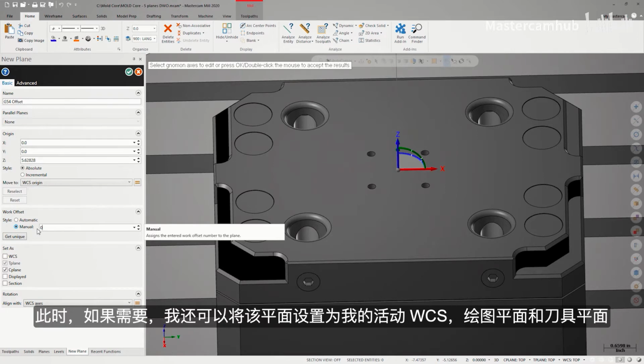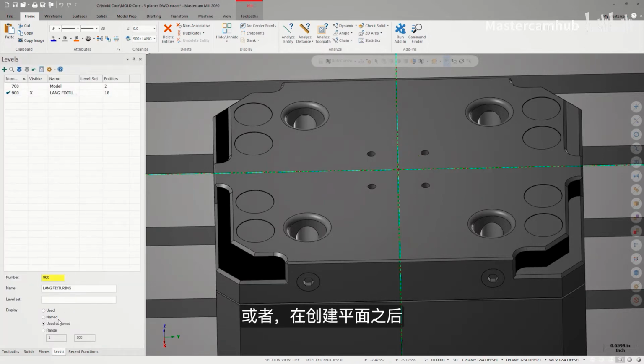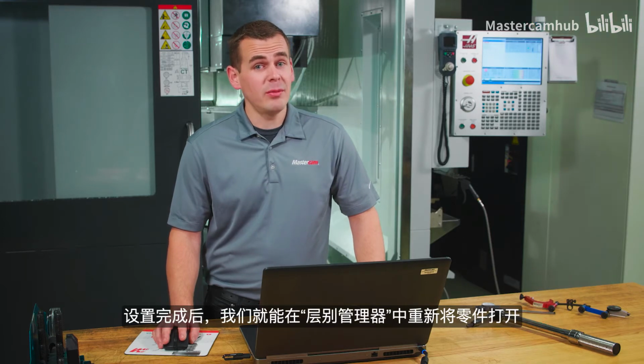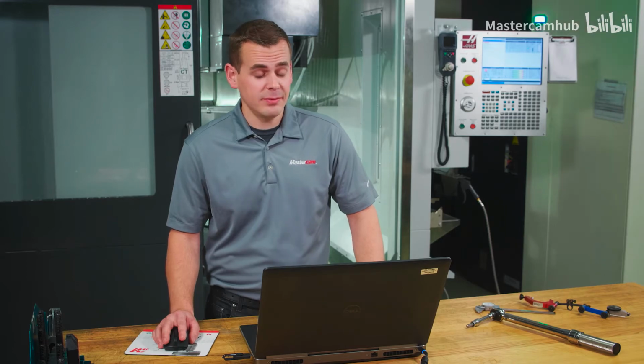At this point, I could also set this plane as my active WCS, construction plane, and tool plane if I wanted. Or, after the plane is created, I could simply make sure it's highlighted in the Planes Manager and click the equals button. With this setup, we can turn the model back on in the Levels Manager and look at machining a feature on the part.